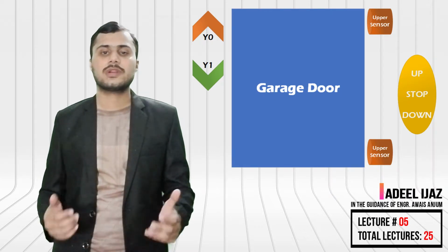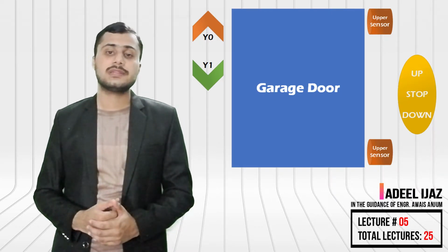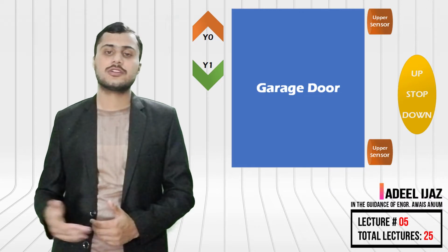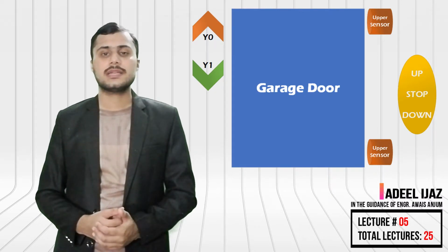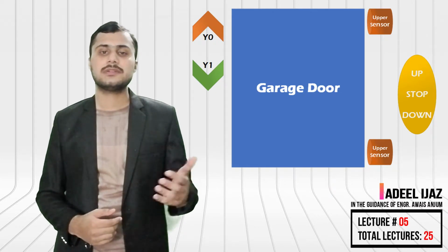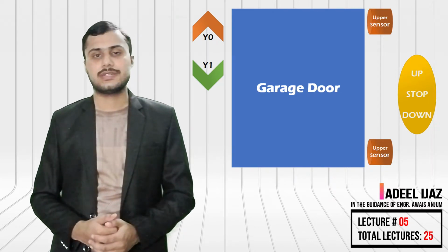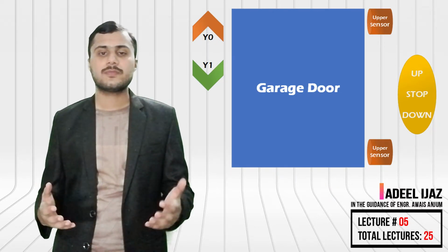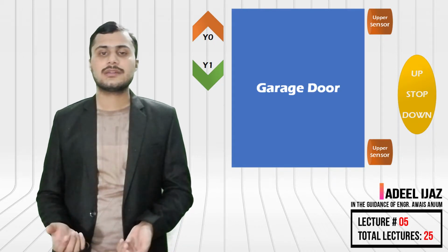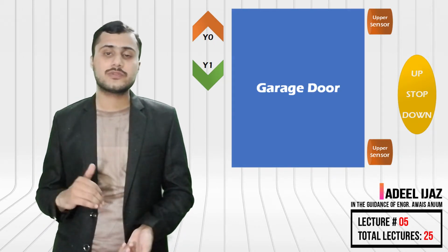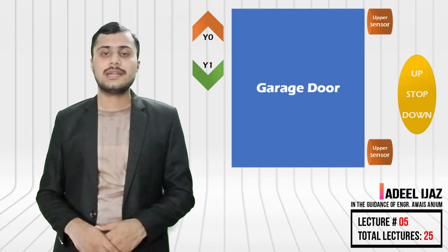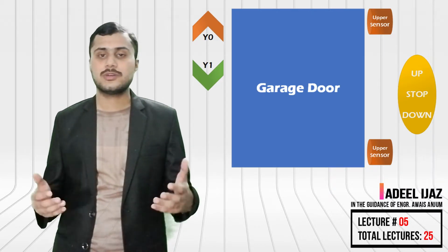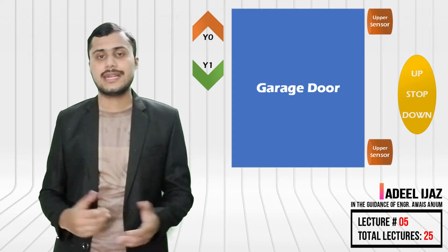Now what our program does is that when we press the up button, the door starts to move in upward direction and stops going up when the sensor attached on the upper side of the door gets activated. Now if we press the down button, then the door starts to move in downward direction and stops going down when the sensor attached on the bottom side of the door gets activated.